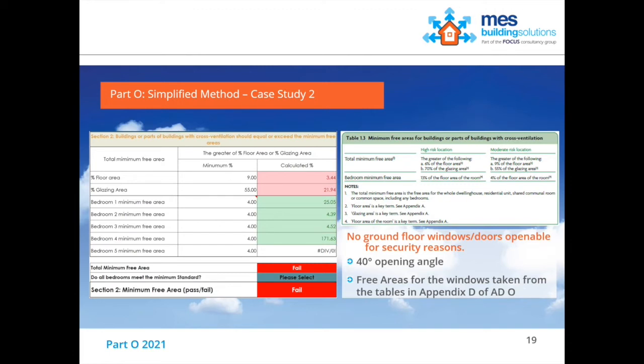We could look at blinds, for example, or movable awnings for those big bifold doors, which would give a large amount of shading and massively help. That's a big double height space, and we know that's likely to overheat. Let's put some automatic opening lights in the roof, because it's open all the way up to the bridge in that area. We can keep those fixed areas, but we can expect the heat, through the stack effect, to purge itself out of that space.